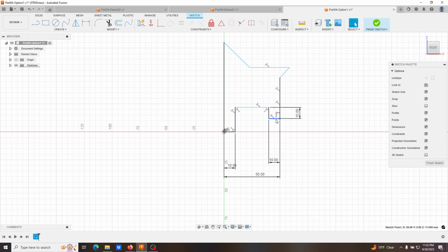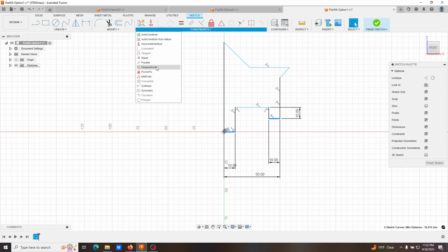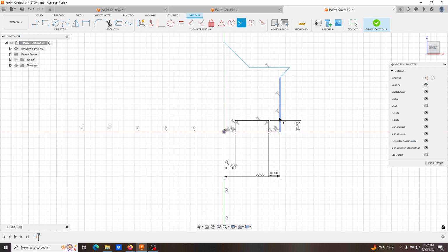Okay, so now that these have been separated by how I dimension them, I'm going to go ahead and add a coincident constraint. And remember, we can attach constraints in a lot of different ways. I'm going to control-select both of these lines. I'll go up to my constraints, and there will be a collinear. So I'll do that, boom, and it'll snap to collinear. Also, please keep in mind that I am still in the coincident constraint, indicated by how my cursor is black, so I can press the escape key. I'll go back to that, and then we can also drag these around.